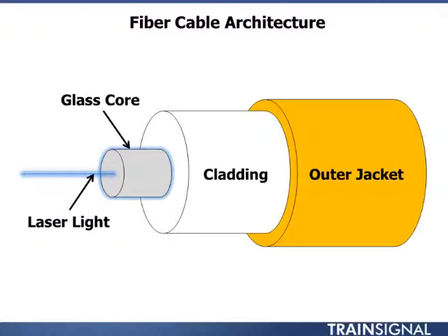One of the great benefits to fiber optic cabling is it's not susceptible to either EMI or RFI, electromagnetic interference, or radio frequency interference. And it's not like someone can just simply use something of the equivalent of a vampire tap to be able to easily eavesdrop on the line. The other aspect that's very positive is it can go much greater distances depending on the lasers that are used as part of the infrastructure.